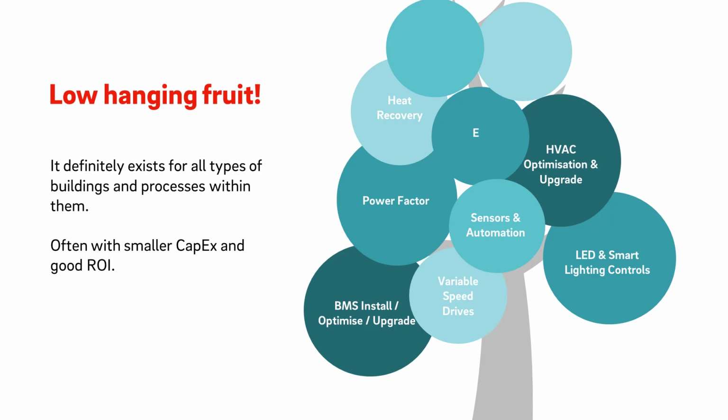However, there's a belief that there's maybe not such low-hanging fruit available out there, and most investments will have a return on investment of around 3 years. Energy-saving projects such as LED replacement have been mainly carried out, or they've become part of the maintenance regime. Greater savings can be achieved by including smart lighting controls as part of these upgrades, so they should be considered when doing these types of works.